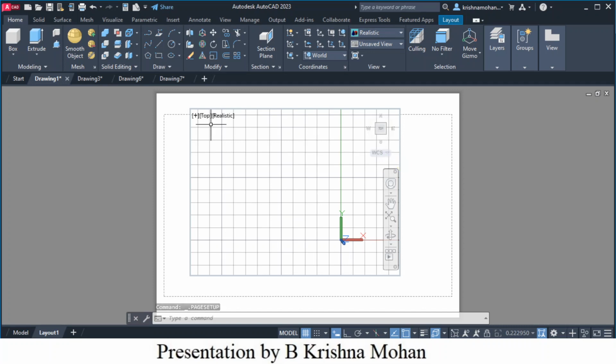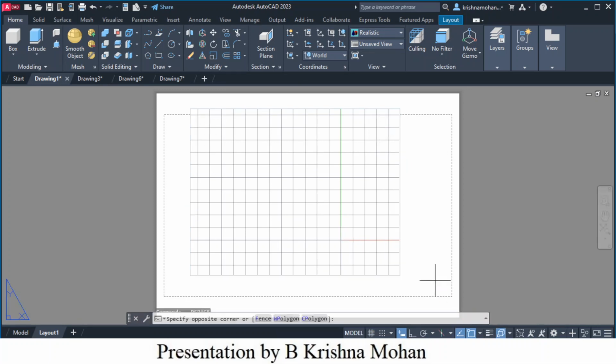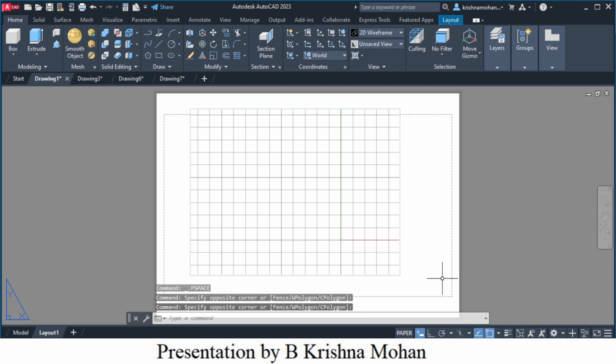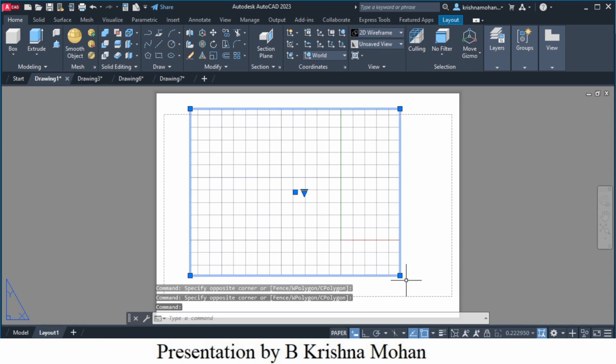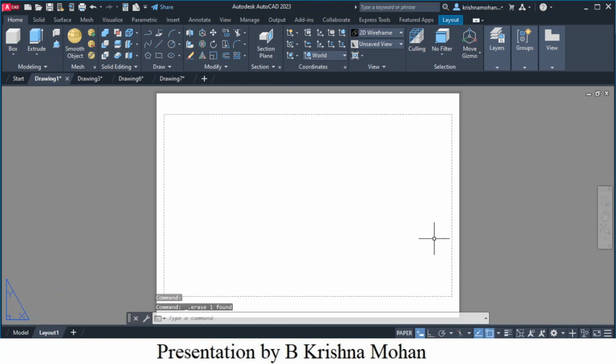So you'll have this viewport area. I'm going to delete this initially. To delete it, first click on the empty space. Then select this rectangular box. This is actually the viewport area. At present you are unable to view anything. I don't want this. I just want to create the views based on the model that we created. So I'm deleting that viewport.